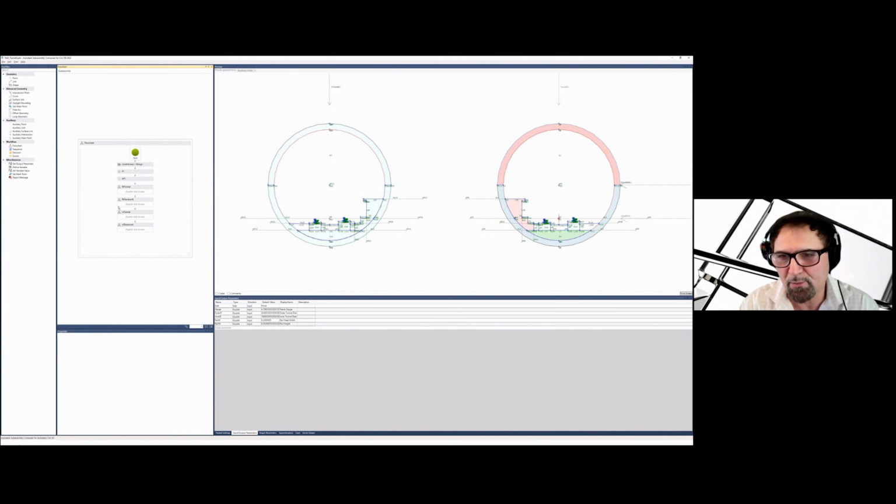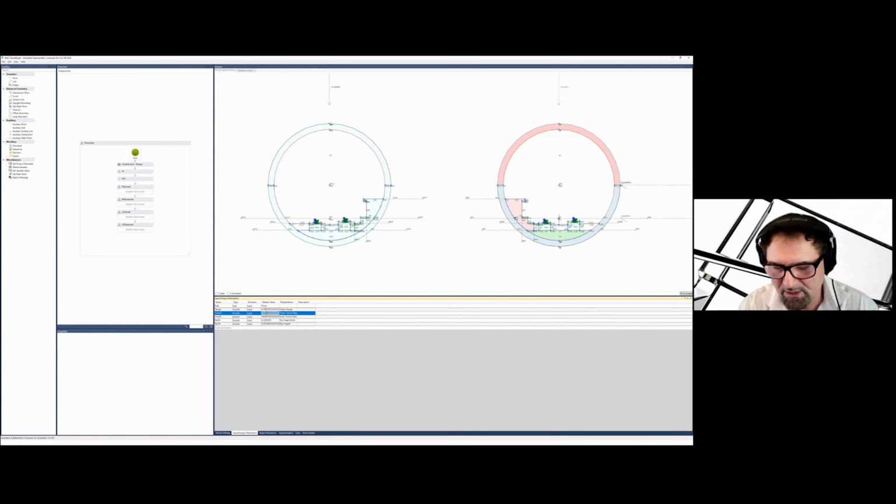This is the Composer file for those two tunnels. What I like about using Subassembly Composer is simply the ability to control my own input parameters. In this example, we are using some flexible properties. The one that is my favorite is the ability to change the diameter of the tunnel structure.